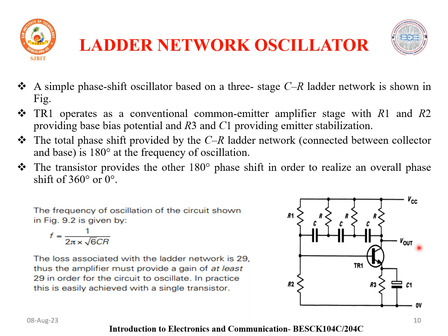That's why we consider the frequency equation f equals 1 divided by 2 pi root 6 RC. R and C are the components used in the ladder network.